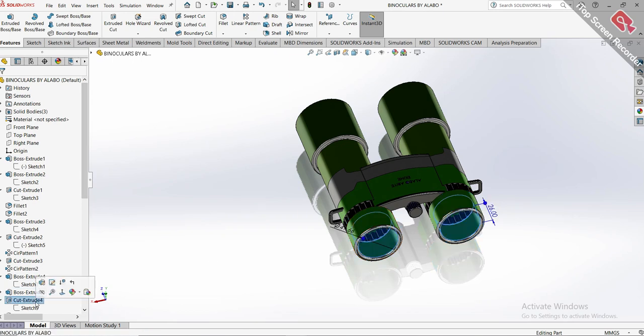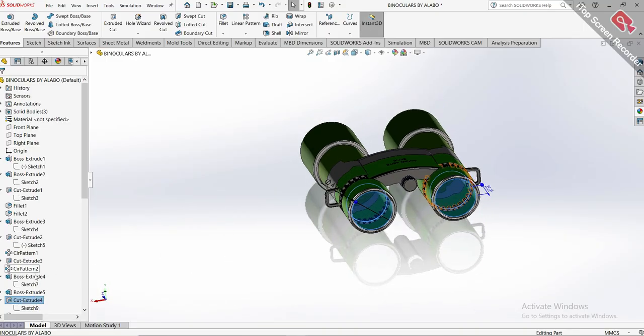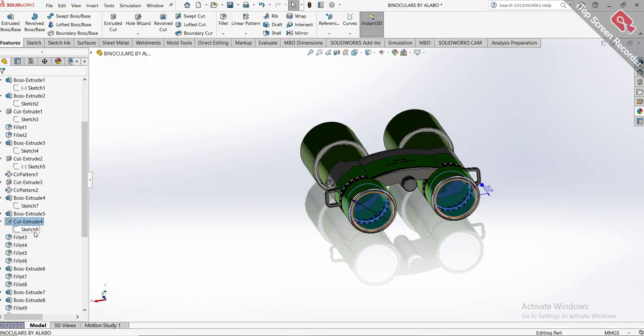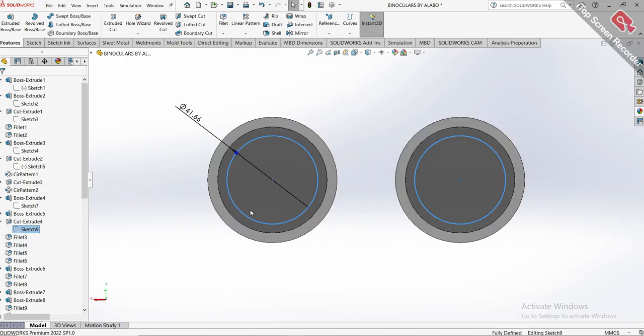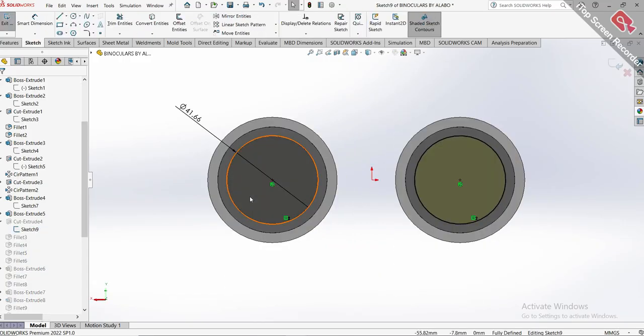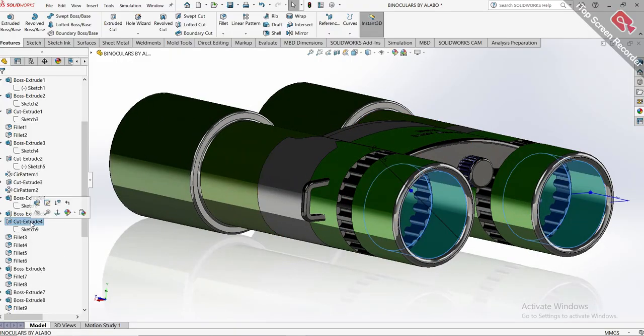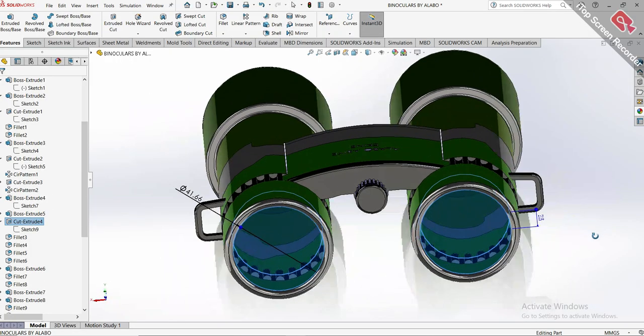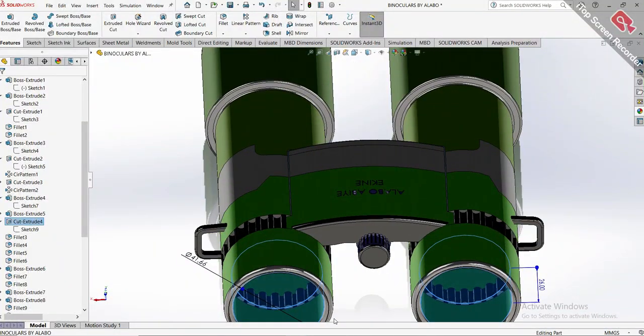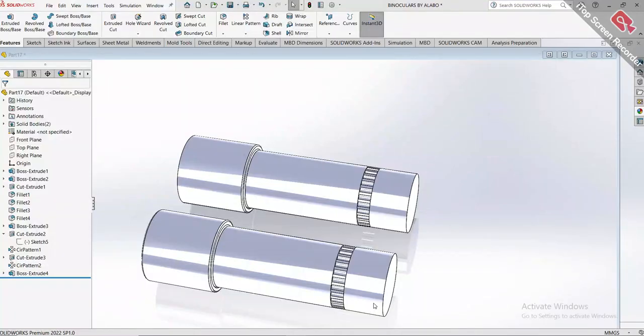We want to cut. So click extrude cut to come here so that we can make sure that we're on track. Come to this sketch. So a circle of 41.666. The circle of 41.66. Then we have the thickness. The cut will be 26. 41.66, cut of 26.